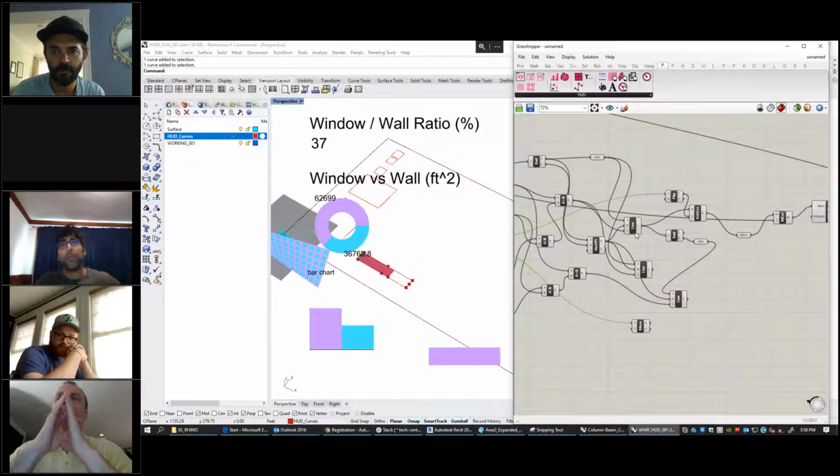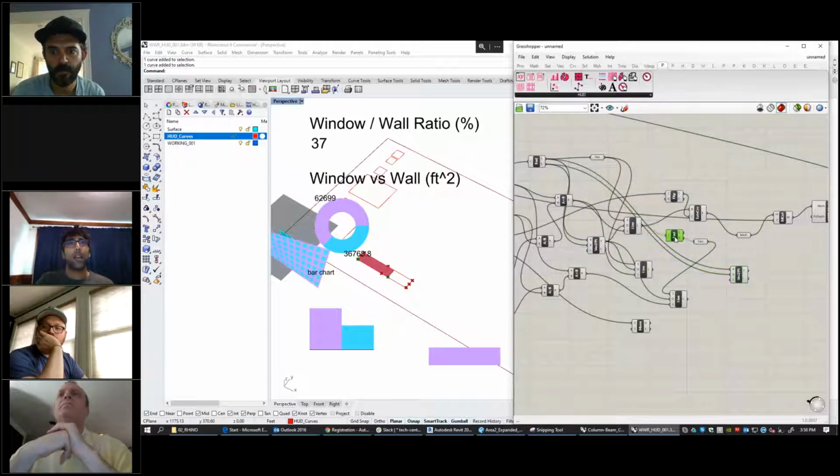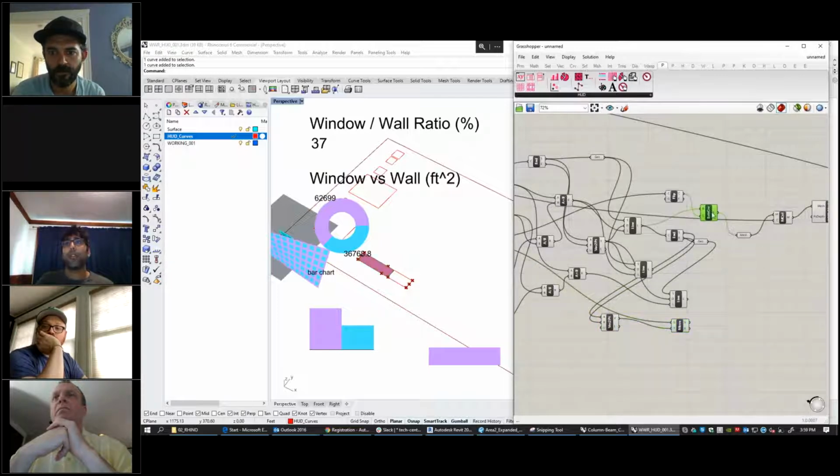And what's actually fun is that we can use the vector that we made with this guy, or no, we're not going to use that vector. We're going to use a vector that we make with this guy to move it. So we're going to use the start point and the end point and move it. Now we can do extrude curve, extrude this curve with this line. And again, I got to flip it. That's always fun.